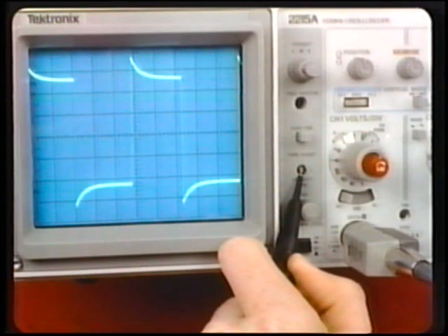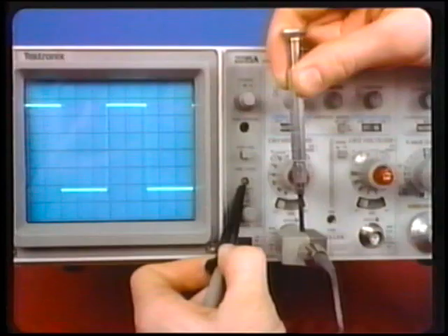Next, the oscilloscope probe should be calibrated and tested every time the unit is turned on. This will verify that both the oscilloscope and the probe are functioning properly. To calibrate the probe, touch the spring-loaded hook to the probe adjust test point located in the first block. A square wave should be displayed. With a small screwdriver, adjust the probe compensation adjustment screw to obtain a waveform that has flat horizontal lines. The oscilloscope is now prepared to display waveforms and make accurate measurements.